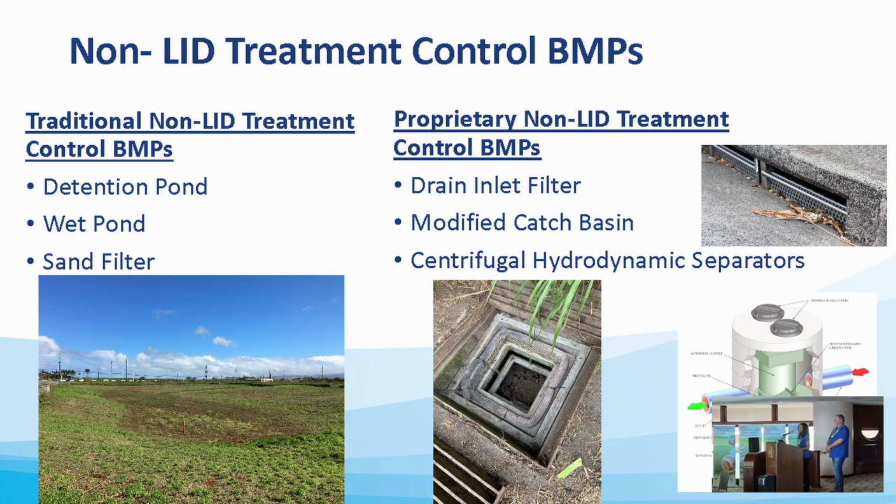And then we have the non-LID treatment control BMPs, where the most typical one that we have is the traditional detention pond, which is very common and provides treatment through settling. Then there are some proprietary non-LID treatment control BMPs that I've shared here that were installed on DOT projects, but this does not necessarily mean that DOT is endorsing these or that they have an approved list.